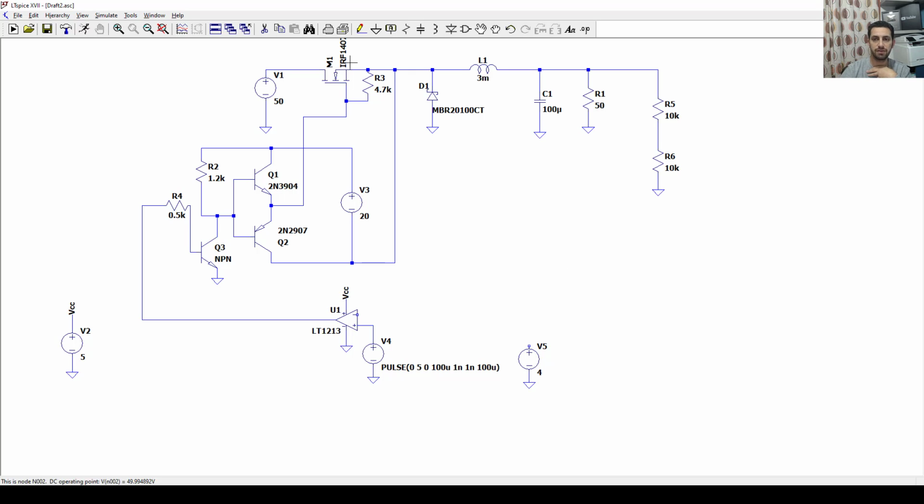What is my desired value. So again, we need a comparator, because we know that the feedback system goes to a comparator, or summation and subtraction. So I will implement here something called on-off control. On-off control means if my feedback tells me that I'm higher than my desired value, it will turn off the buck converter or the MOSFET.